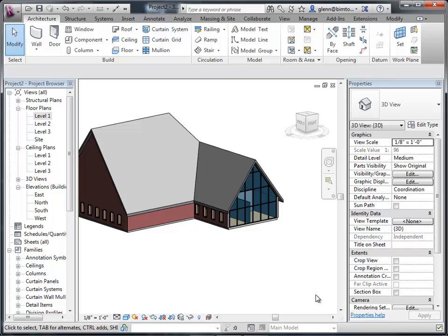Also, we'll take a look at basically how we get these things and start to create the views, making floor plan views with dimensions on them, making elevation views and getting those on sheets. But between that, you can spend a little time just working on your shape. Again, it's only 500 square feet, don't over-design it. See if you can get a basic little building that's kind of together like this, then we'll have something to operate on in the afternoon. Okay, yes?